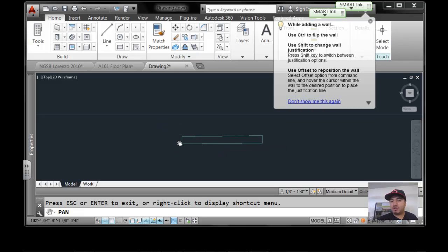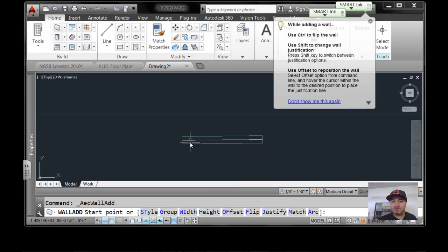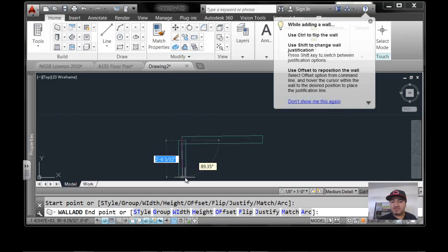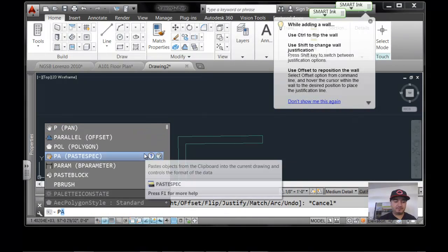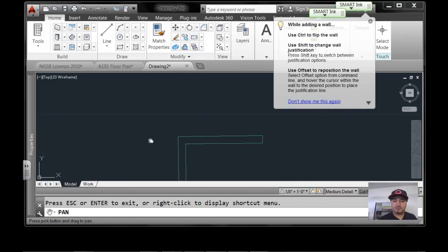To add more walls, you can do it from the corners, which automatically does, or you can intersect it through the middle. It's optional, but I'll give you a brief example. You can do it from here. Let's say another 3 foot wall. Click 3 feet, and it's right there. Hit escape, and it's right there at an intersection. And that's how you make a wall. You can intersect them or make them throughout the whole house. Beautiful, thank you.